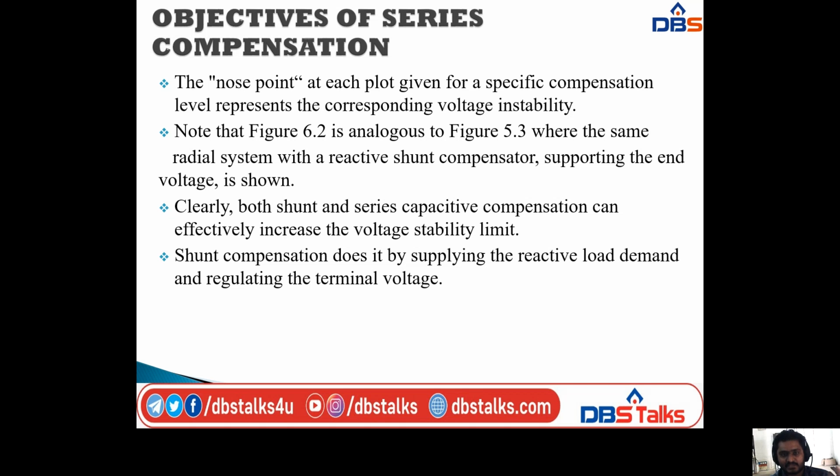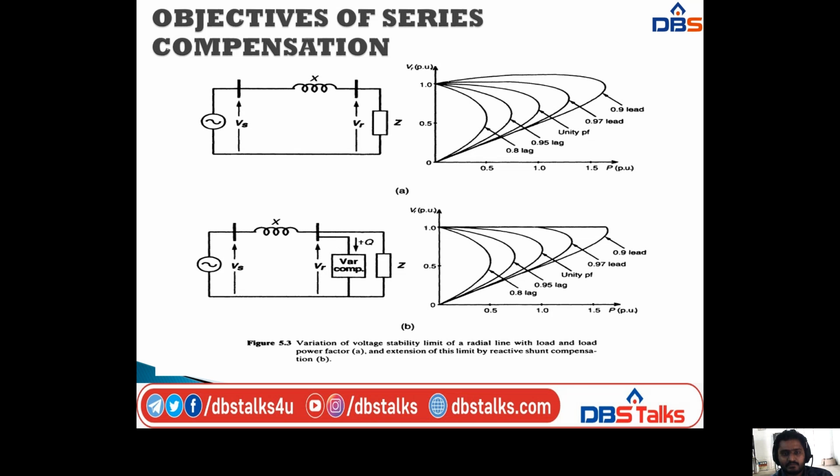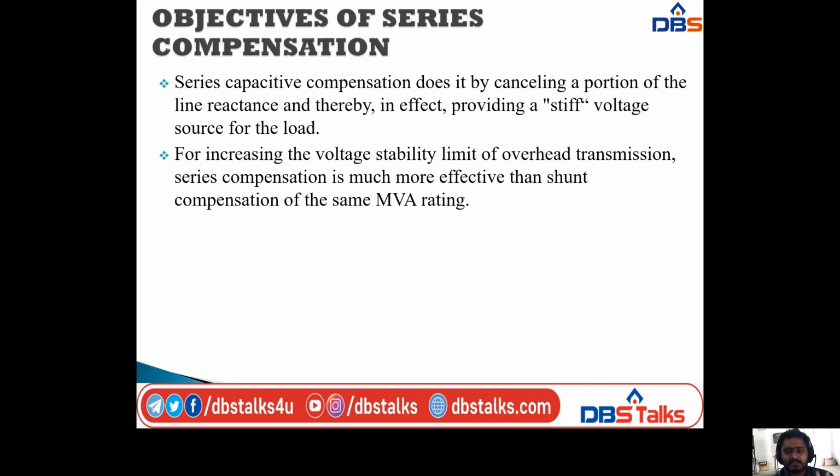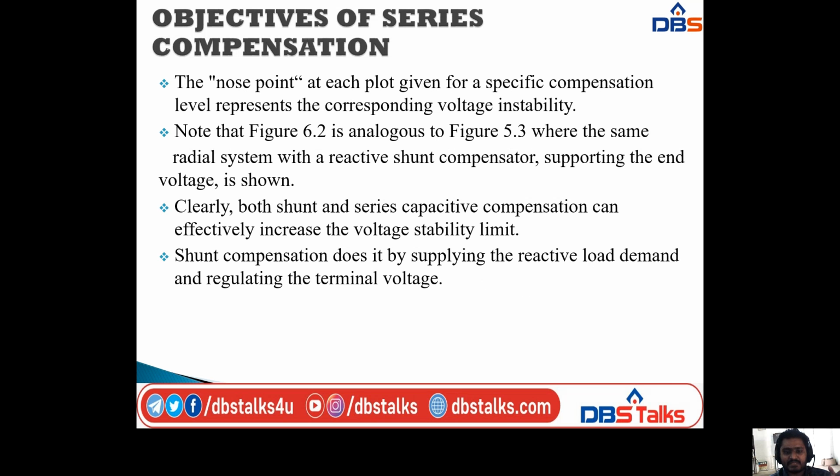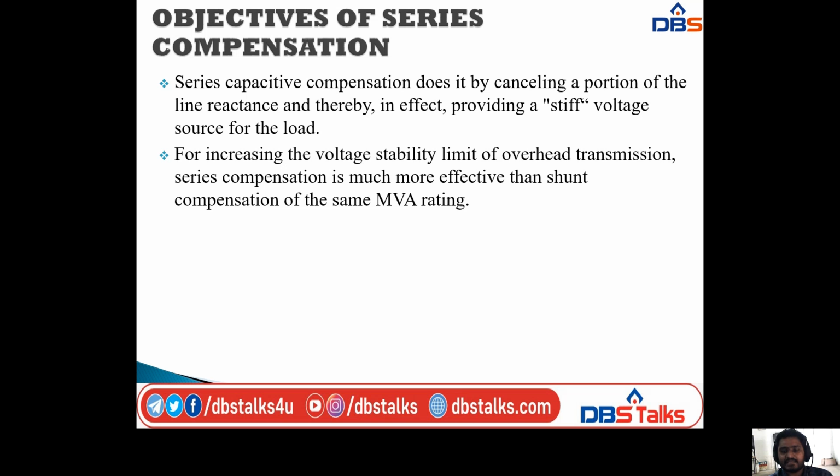And series capacitive compensation does it by cancelling a portion of the line reactance and thereby in effect providing a stiff voltage source for the load.